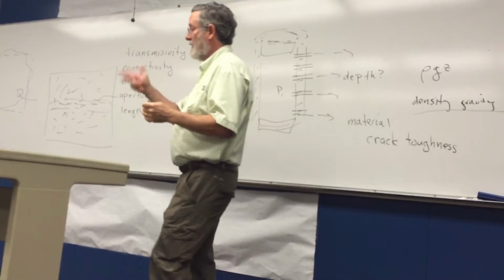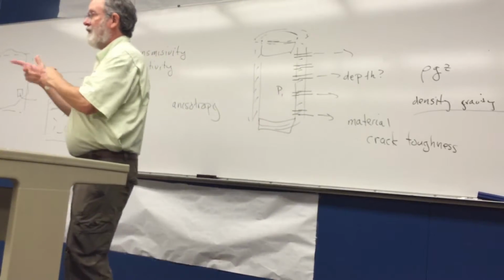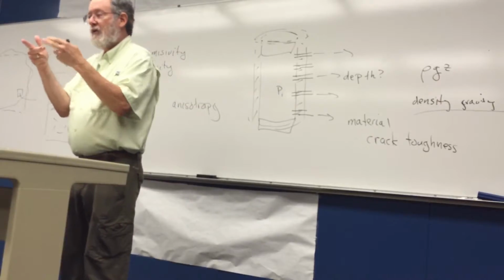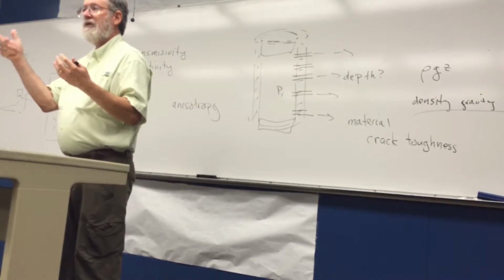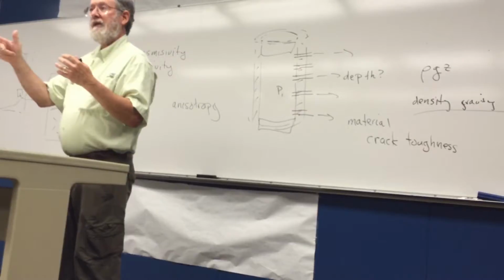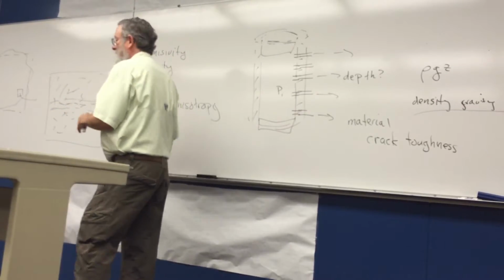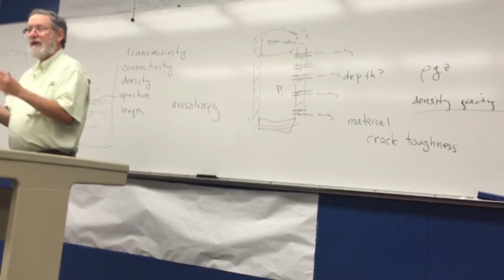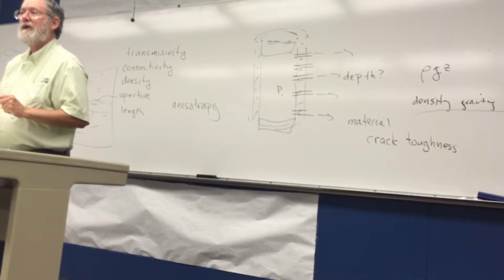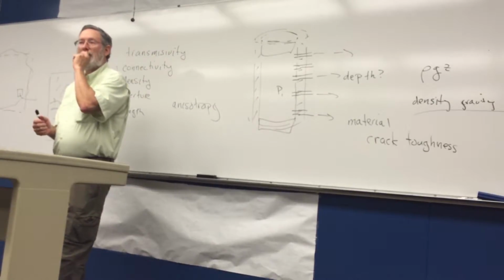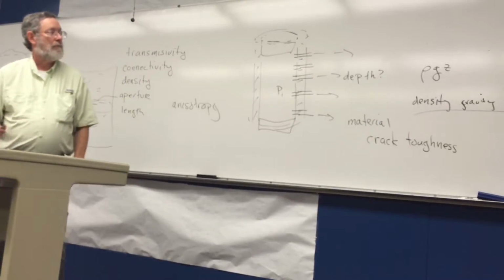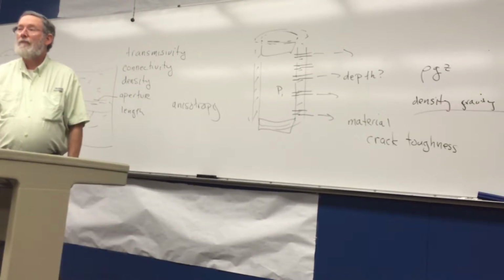And we typically will express it in an XYZ or a 1, 2, 3 coordinate system for looking at the anisotropy. And then that anisotropy is actually a tensor property. It's ellipsoidal in nature.